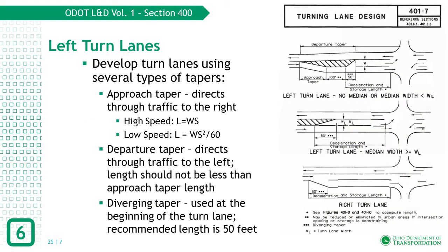Figure 401-7 shows how to develop the left turn lanes. When determining the approach taper, which is the taper used to shift the through traffic to the right, determine whether your roadway is a high-speed or low-speed facility and use the correct taper equation.